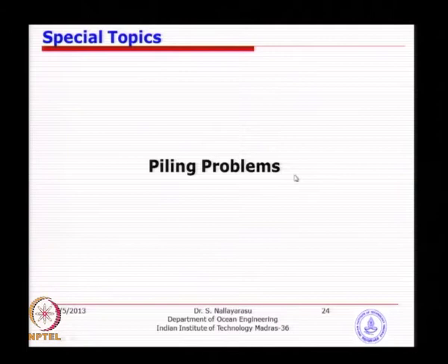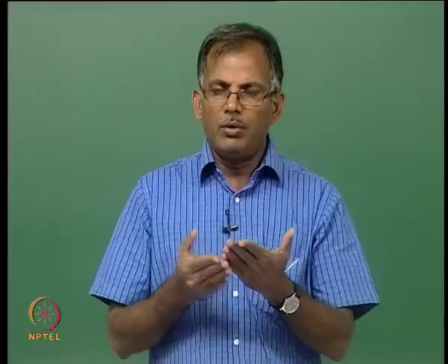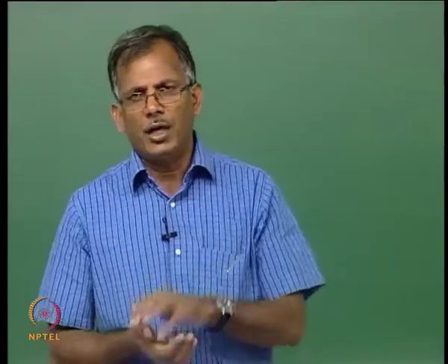The last one I think we want to see today is basically the piling problems. We have learned about pile drivability. During driving, if you expect premature refusal, because you already have reviewed the soil layers and the soil layer seems to be very hard, and you do a theoretical assessment that this hammer is required, still you get prepared for some kind of remedial measures. In case it happens offshore, you do not want to come back and then go again. So you actually get prepared, because the repercussion is very large.